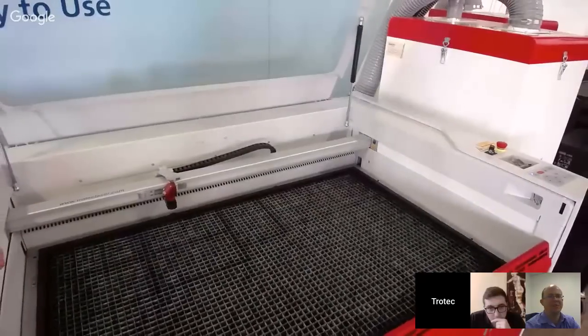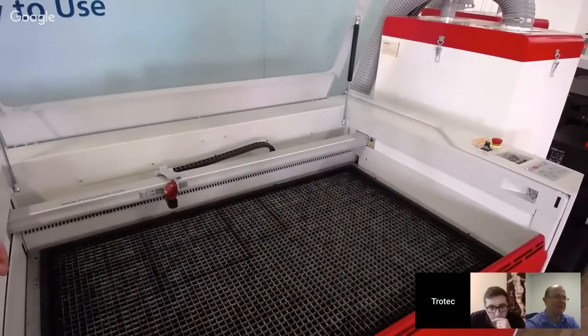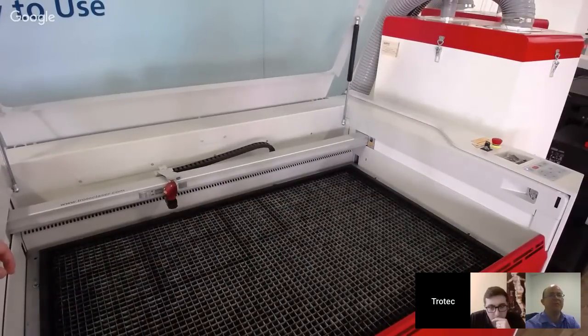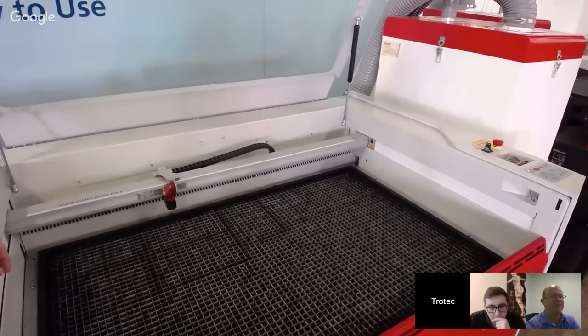Many people, I'm sure, if you've ever tried to engrave red and white plastic, that's always the nightmare combination, because if you're engraving top down, you end up with pink engraving instead of white. And that's because that red smoke has gone in and it's stuck to the sticky white inside material, and it's turned it pink on you. So to avoid that, we engrave bottom up. So what it does now is it's sucking that red smoke across red surface material, and it doesn't color it anymore. So that's how you get that nice white engraving.